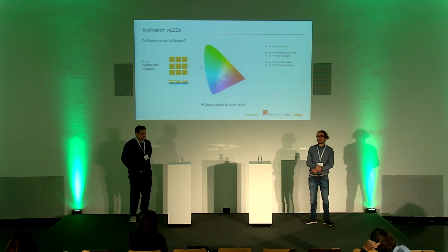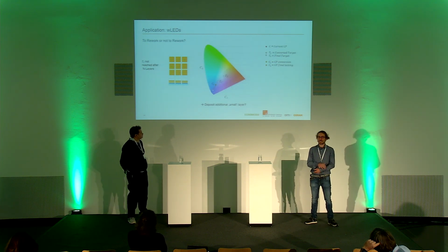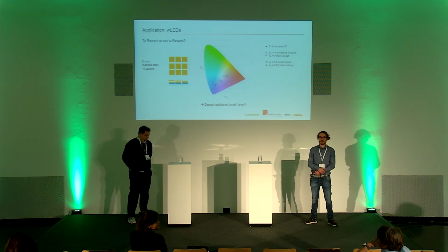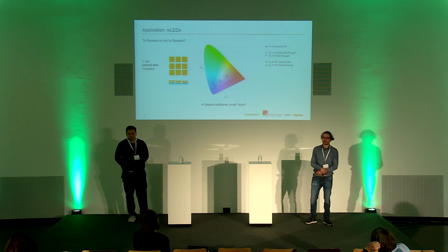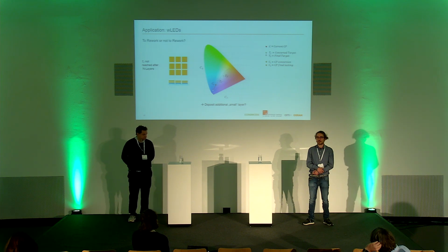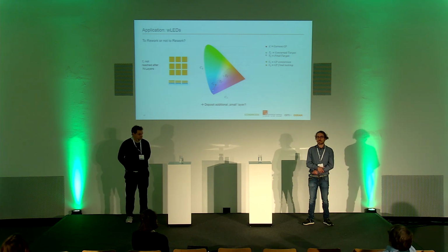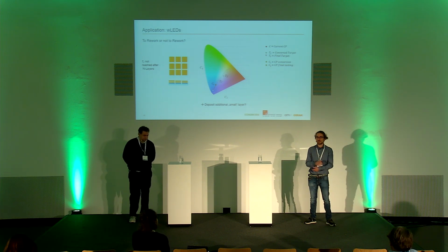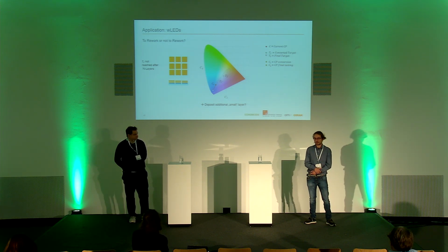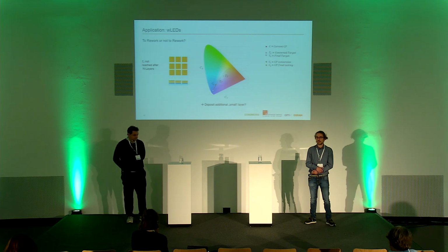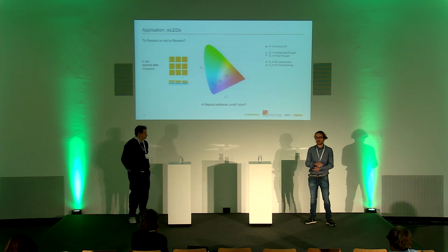So sometimes it happens that despite sticking very closely to the recipe, we fall short on this conversion curve. And our product engineers, process engineers came up with a solution for this. They said, hey, why not apply one additional phosphor coating layer to it? And again, like with the cookies, the question is raised to rework or not to rework. And for this question, we can use the information we have, that is this color point C1 after the end of the regular conversion process.